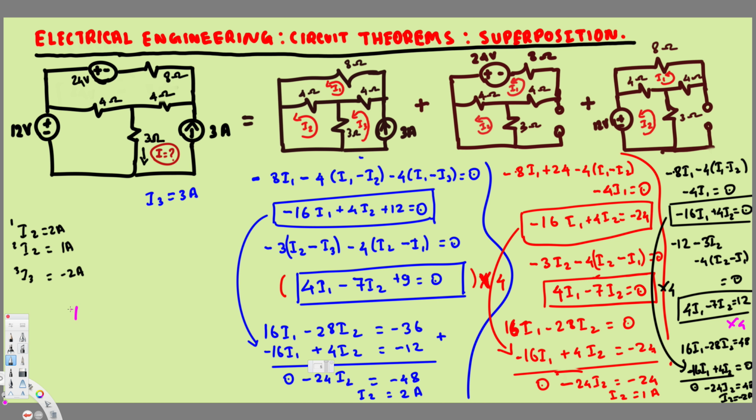Therefore I is going to be equal to, this is the direction of this I current, and if you look at the meshes, I3 is going along the current's direction, so we are going to have 3 ampere positive. Okay, and I2, we took it in the opposite direction of this direction, so whatever the I2 value we get, we should put the opposite sign for that.